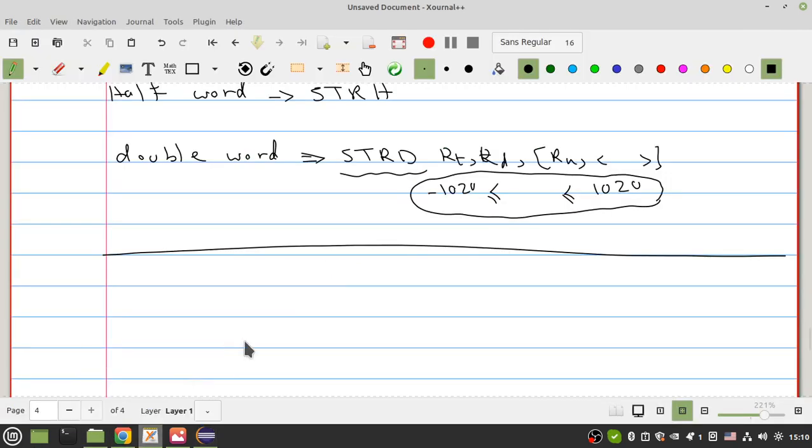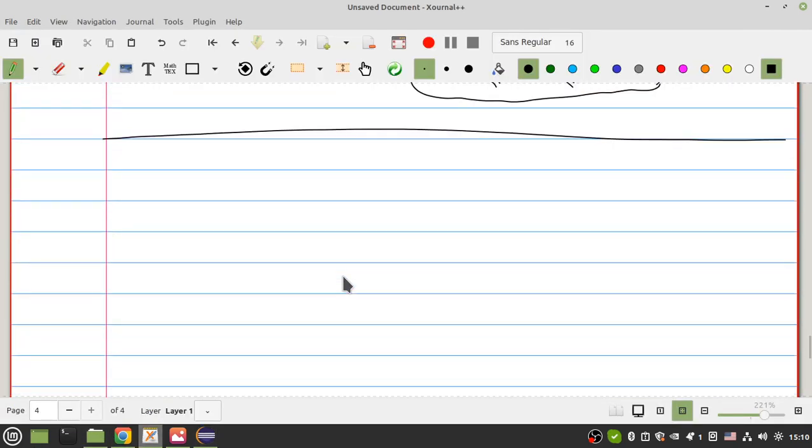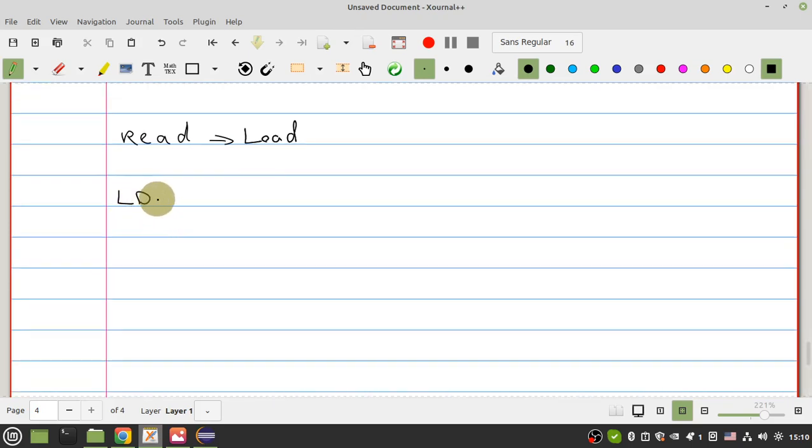This was about the store instruction, writing to memory. But what about reading from memory, the load instruction? The instruction is LDR, and other options are completely like str. For example, you can load a value with an offset into register Rd, this time from your memory.